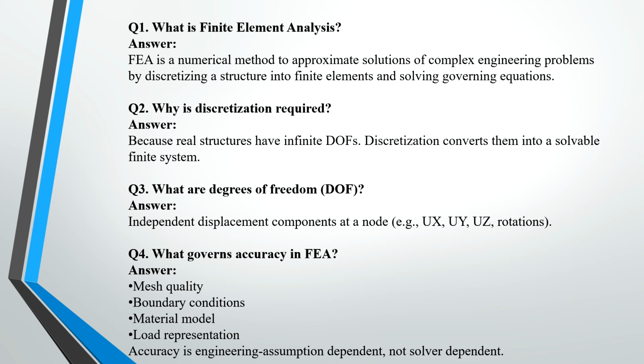So what are the governing equations in FEA? What governs the accuracy in FEA? So the answer is the quality of mesh, the boundary conditions, material model, and load representation. The accuracy depends on the engineering assumptions. So whatever assumptions we make, the accuracy depends on them, not on the solver.